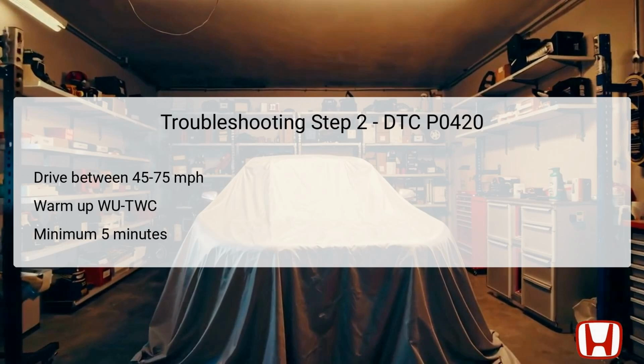This step is essential for adequately warming up the rear TWC, as catalytic converters require a specific temperature range to function effectively. The extended driving time in this speed range promotes thermal efficiency and allows for accurate monitoring of the exhaust emissions. A warm catalytic converter performs optimally, facilitating the conversion of exhaust gases while providing the PCM with accurate input from the secondary HO2S. Successfully conducting this step is critical for determining any persistent issues affecting catalytic efficiency and assessing the overall integrity of the exhaust system components.